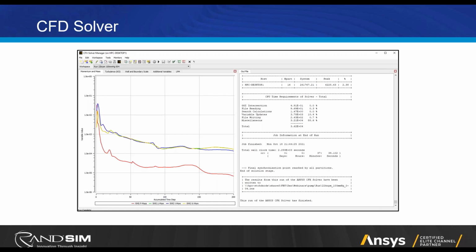You're marching on. These are iterations down here. And you generally want these residuals or the imbalance to be decreasing with time. So you're getting closer to a converged solution. I don't show it here, but you can also monitor values, different things in your domain, which is also a very good indicator whether it's converged or not. In this case, maybe look at the pressure at the outlet, for instance, and see when it's changing. Or if you're calculating the flow rate, which is also done sometimes, you can monitor that and see when that stops changing. So basically, a steady state solution like this will be converged when residuals are relatively low and the variables you're solving for are not changing with time or iteration, I should say.